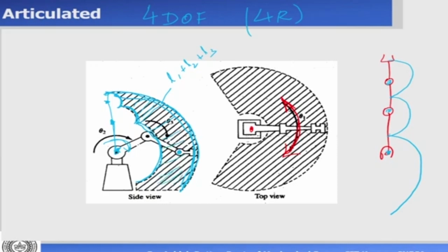So this is the shape from the side view of the work volume, making an assumption that your theta 2, theta 3, and theta 4 have joint limits of about 180 degrees. That means they cannot rotate 360 degrees. If they rotate 360 degrees, the shape will be different.